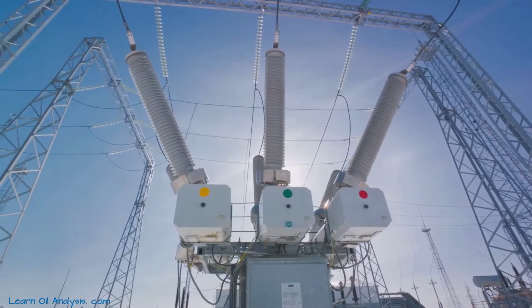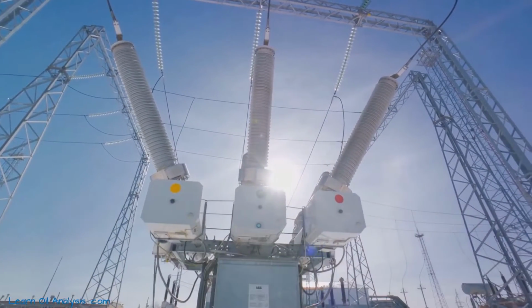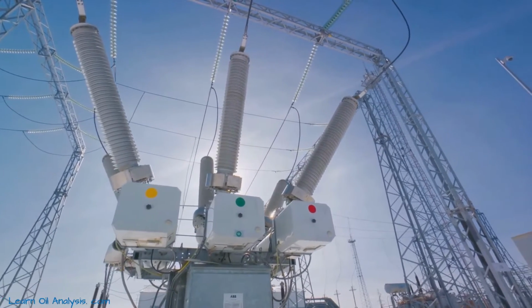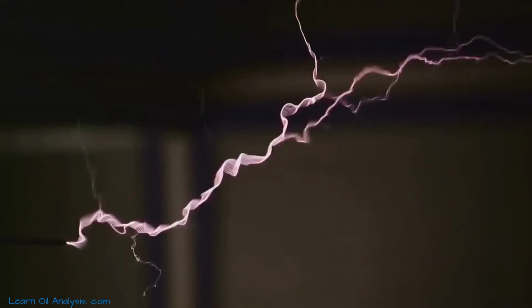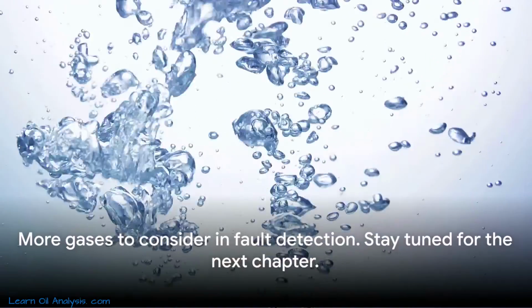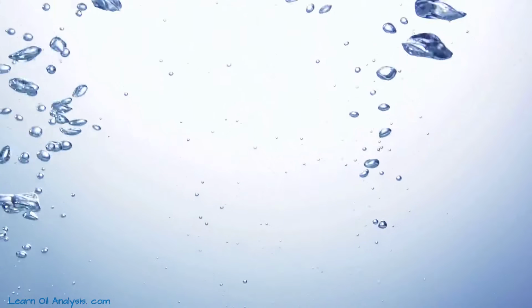In a nutshell, hydrogen is a key sign of partial discharge, while the presence of acetylene can indicate a more severe high energy or arcing fault. Remember, early detection is crucial in preventing further damage and ensuring the longevity of your transformers. Hydrogen and acetylene are important indicators of faults, but there are more gases to consider. So, stay tuned as we continue our journey through the world of DGA, exploring more fault types and their corresponding key gases. It's a fascinating world, and we're just getting started.